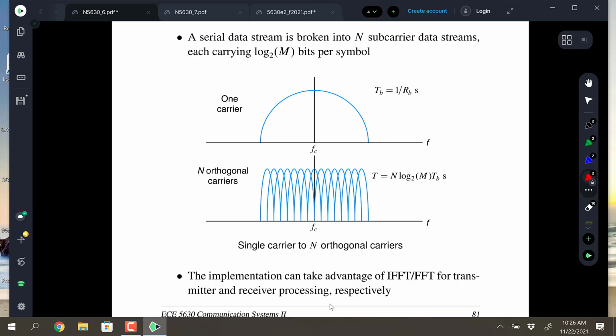But the bands that I have plotted there as being orthogonal are the idealized frequency responses you would get for each bin in an FFT. They have an orthogonal relationship by virtue of the fact that the FFT center bin frequencies are orthogonal to each other, right? You have N frequencies in the FFT, and the period is N in the FFT itself, so that means that those frequencies are mutually orthogonal, and that sets up a nice way of doing things.